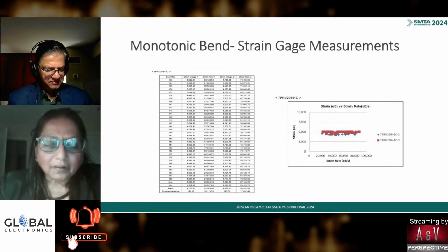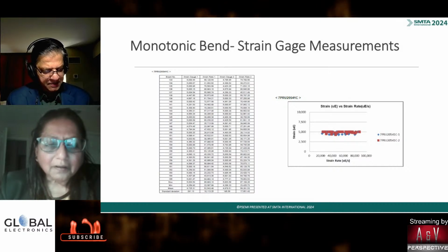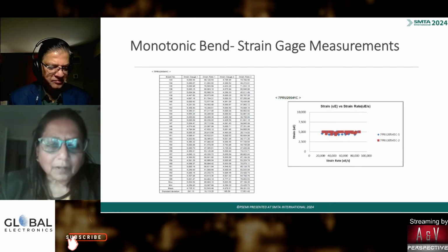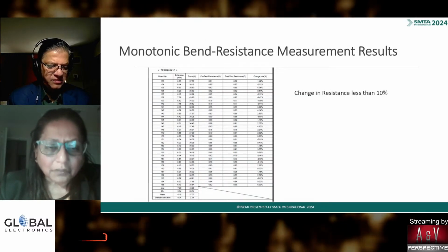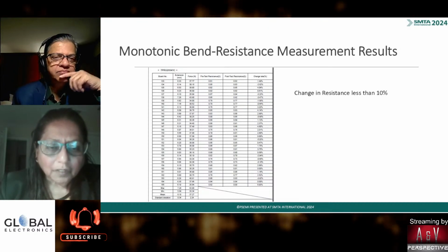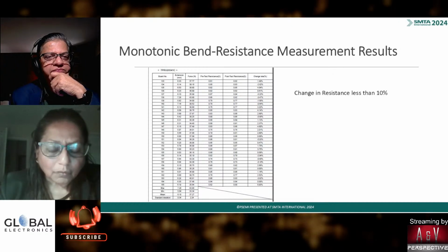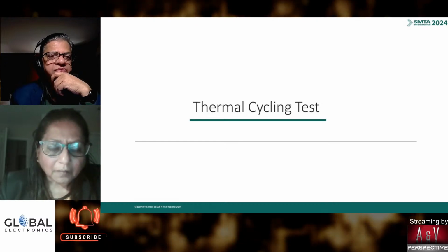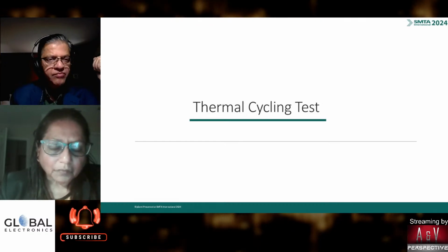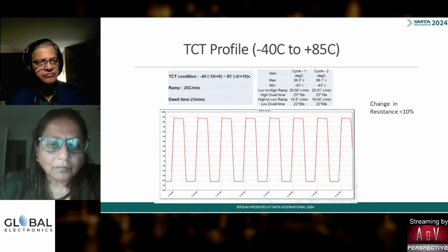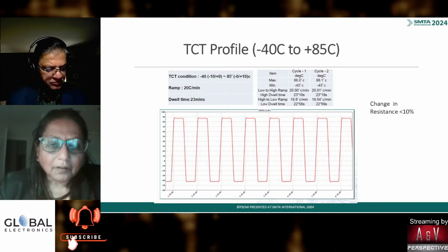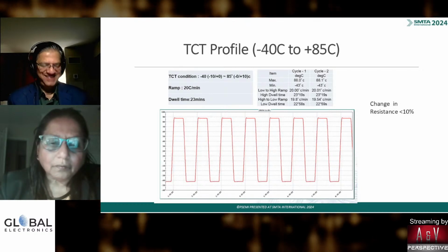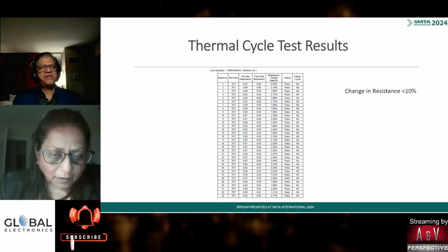As the nodes get tighter and tighter at the silicon level, and we go to tighter and tighter pitch on components. Currently the surface mount industry is successfully doing 0.4 millimeter pitch in HVM. Now our customers are requiring us to go to 0.3 millimeter pitch and further. At the same time, a lot of integration is happening at the silicon level, so things are getting finer and tighter. From the design standpoint for PCB, yes, we have to prepare for fine traces, fine spaces. We are going to ultra HDI.